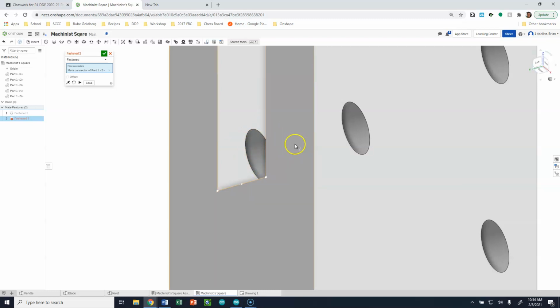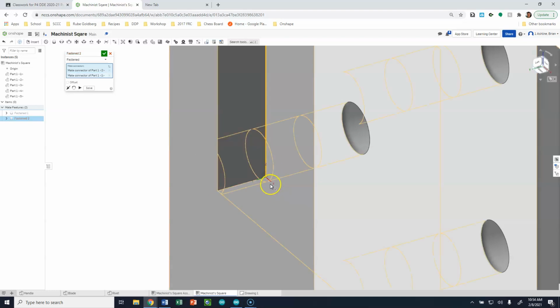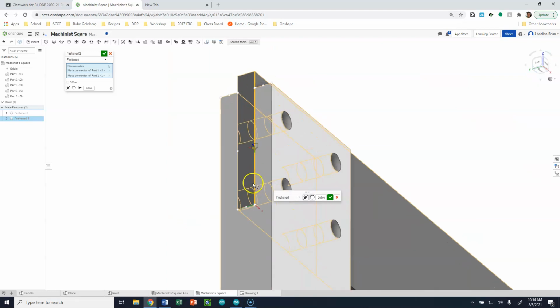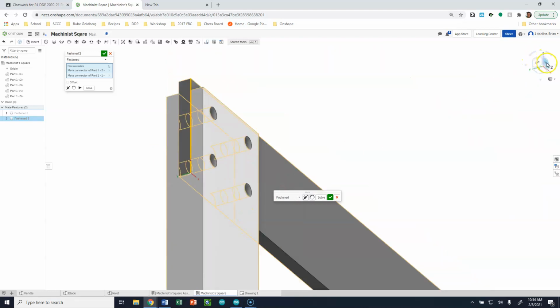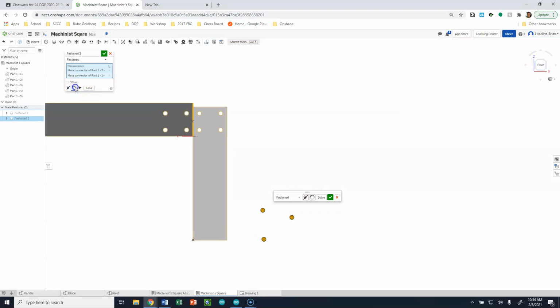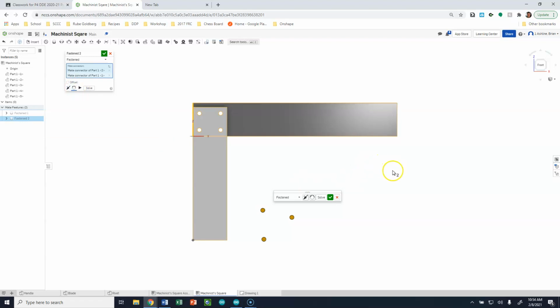If you just hover over a surface and then hold the shift key, then it will only select options on that surface. Okay, so let's, although it seems like it's also, there we go. There I was just able to attach that. Okay, so now I have these two pieces connected. And again, if things weren't quite right, I could mess around with reorienting that piece. Then I can click the checkbox.